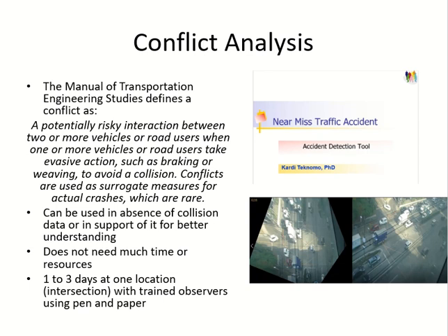So the vehicle was going straight and then it went like this. There was nobody else on the road. It's just a conflict, so it's a potential accident. Whether there was another road user or not is not the case. It doesn't matter. These studies are shorter, and they can provide you more data as compared to crashes. Crashes you may have like one in a week on a highway, but in 1 hour you can maybe observe like 100 conflicts. It can happen.